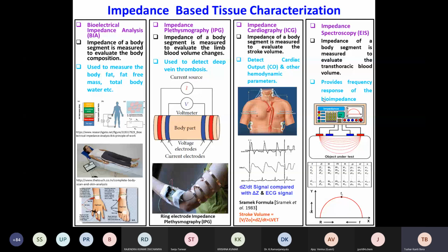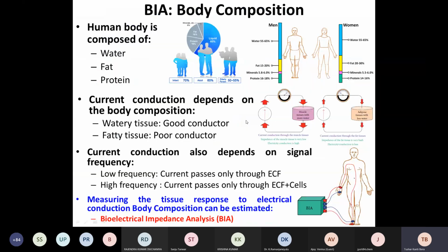Recently, the carbon fiber reinforced composite, known as CFRP, is very popular for its high strength to weight ratio, and it is replacing aluminum in aeroplane construction. That type of composite material can be monitored either offline or online for damage detection, or for detecting any kind of crack inside it, with electrical impedance techniques like electrical impedance spectroscopy.